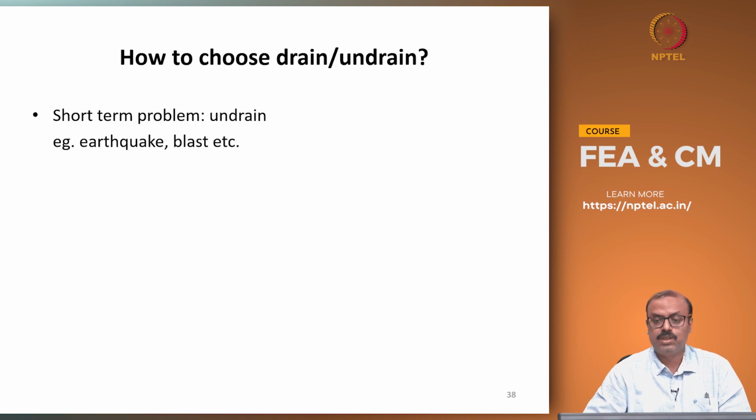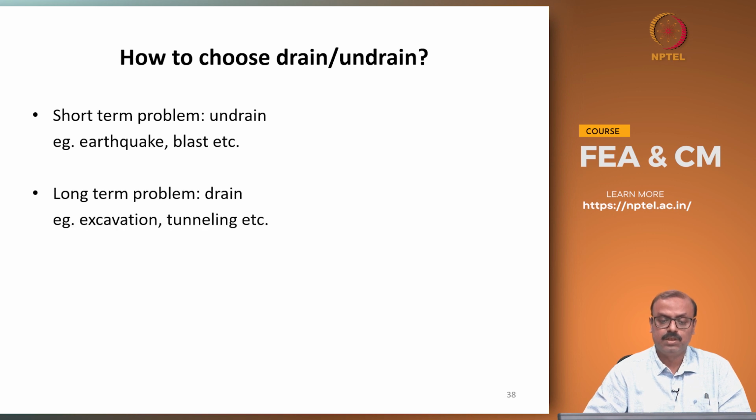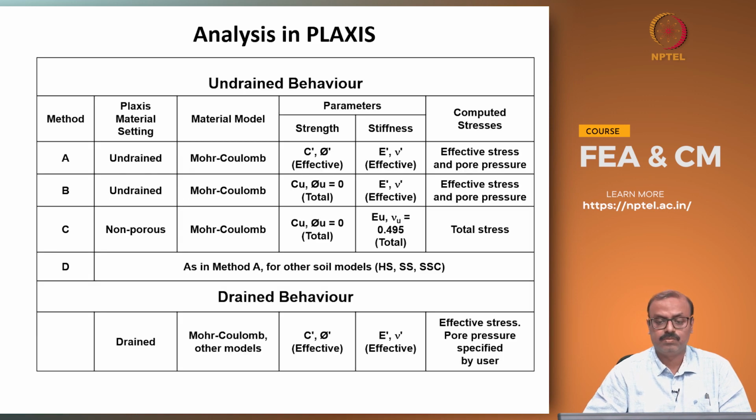So, how to choose drained or undrained? Undrained we generally call a short term problem, like earthquakes and blasts, where you are not allowing the excess pore pressure to dissipate. Long term problems are excavation, tunneling and so on, because here long term performance is the key issue, particularly if you talk about cohesive material.